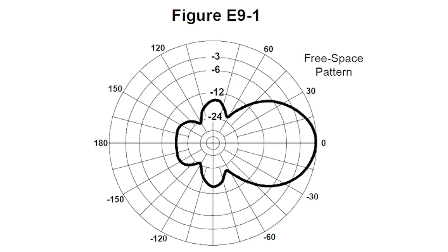You see there's different sizes of rings in that chart. The outer ring would be 0 dB, because the very tip of our antenna pattern hits right at 0 dB. It's referenced against the main lobe of the antenna. The next circle down would be minus 3 dB, the next one minus 6, the next minus 12, then minus 24. They don't have the next one marked, but it's probably minus 48.